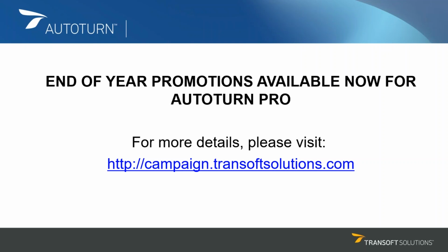Can the software, IntelliPath, be used to model emergency vehicles such as ambulances, turning path, considering that the movement conflicts will occur at reasonably high speeds? You can set the speed for your vehicles independent of which vehicle you're working with, and IntelliPath will give you an estimation of whether a vehicle can make it through or not. The vehicle, as you saw during the presentation, will stop at the last valid position, and it will give you an indication that it cannot go beyond that point.